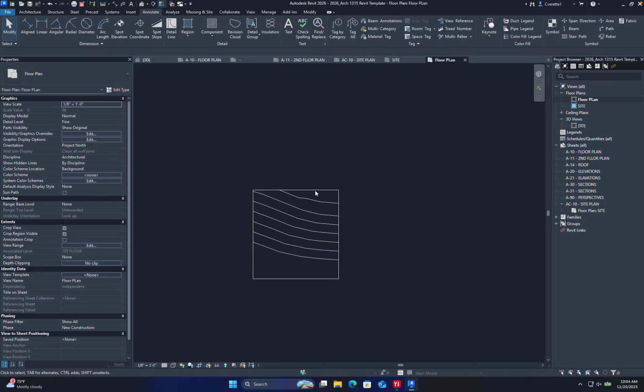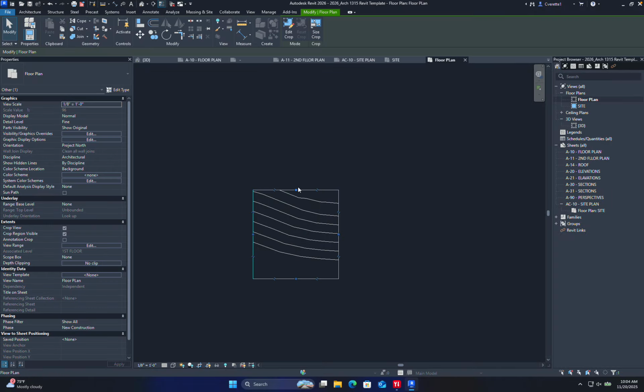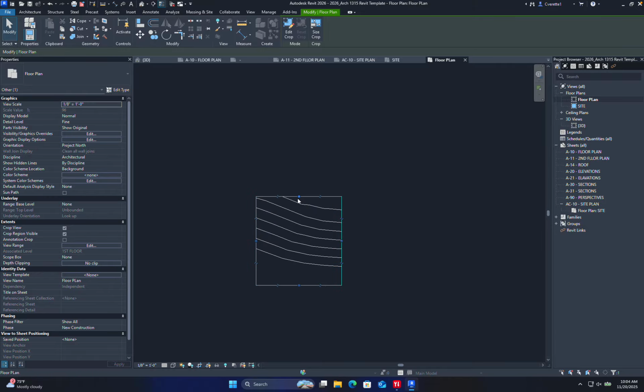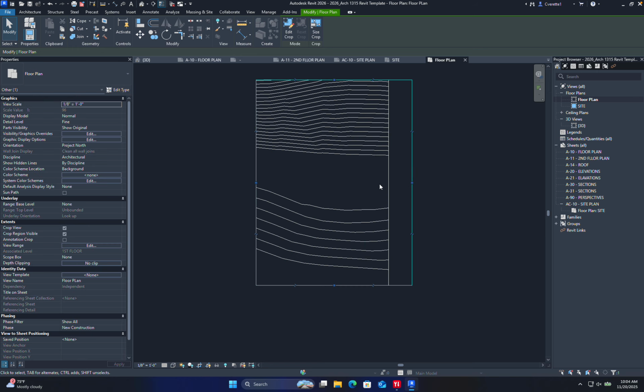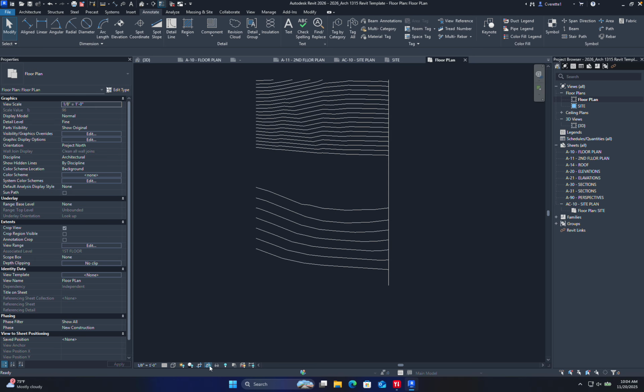And you'll notice, wait a minute, that's not the same amount of area. In fact, I have a viewport boundary involved by default. I did that on purpose so you at least know where to find it. I need to expand my viewport. It can be treated like a crop tool. I can also make it disappear. It's on by default, but to control it, it is called your show crop tool. In my case, I do want that.